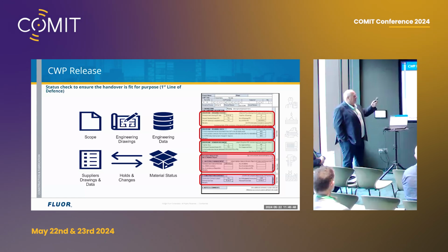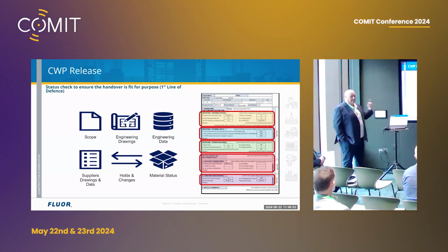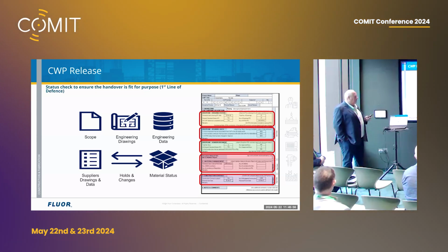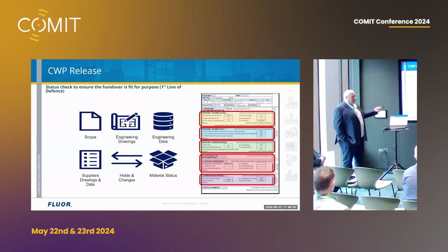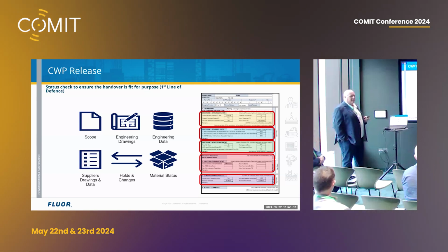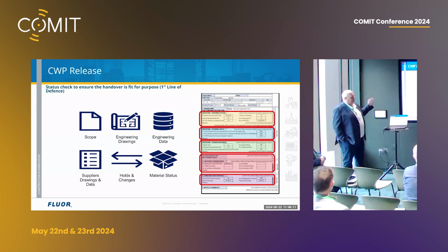Change kills us. Is there actually all the engineering metadata available for our turnover systems or other systems or our tools? Have we got any supplier drawings and data? If we're installing a pump, is there a special way of installing it? If we haven't got that and we install it wrong, it's going to have to come out, get remade, put back in. Even down to the point of thinking, bringing construction in, can we actually install that on site?